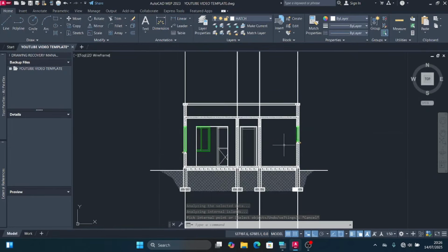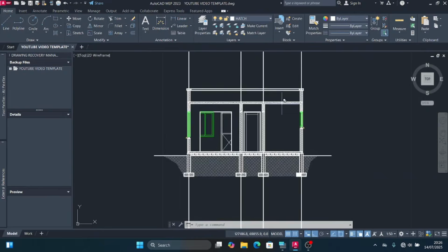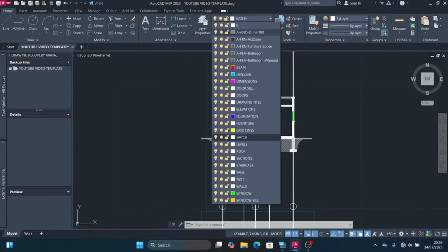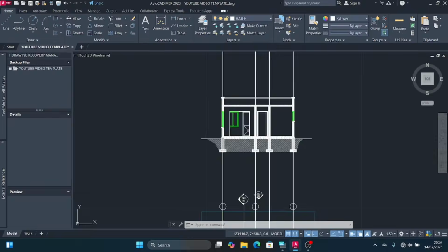I'm going to put a boundary box for this cross section. Alright. So I'll click at this arrow. Select the layer for depth points. Then click at the rectangle command. Then I'll type in 1500 by 1500. Select it. Click at the move command.